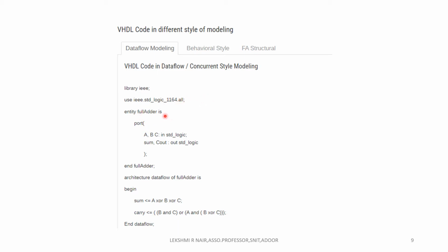The entity full adder is port, define the inputs A, B, C in std_logic, and the outputs sum and Cout, sum and carry, as std_logic. So we define input variables and output variables. Then end full adder, end the entity.